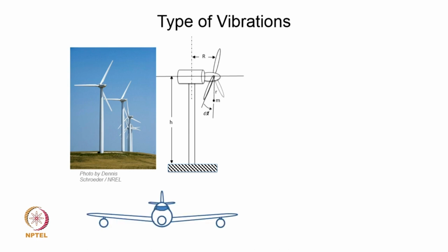So, another example is the wing of an aircraft. If we assume this to be rigid enough, then we can treat this to be a cantilever beam, obviously, right. So, you can have this wing as a cantilever beam, and this cantilever will undergo lateral vibrations based on either excitation from the flowing wind around it, or in addition you may also have excitation from the engine rotation. So, all of them will excite lateral vibrations. Of course, the wings are not as simple as a constant cross section beam, but its cross section can have this kind of an aerofoil section, and then this cross section keeps changing along the length obviously. So, it becomes quite complex in that sense, but as a preliminary study one can estimate the natural frequencies of vibration for such a wing structure.